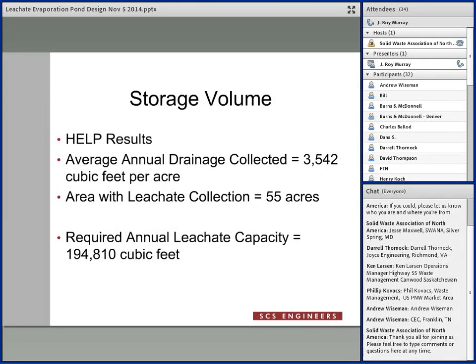So to look at designing the ponds, we're going to look at how much water the ponds can hold within their operating range and how much we expect to evaporate out of there, and that would give us a total capacity for those ponds over the year, with the idea that you can put so much in there, but over the course of the year, as you're putting it in there, it's evaporating. So we'll look at the total operating capacity of these ponds.